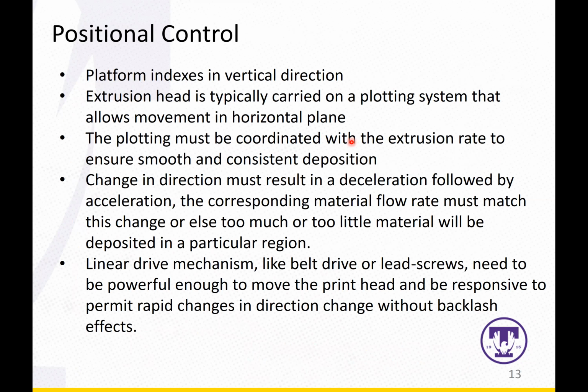So they will extrude a small amount of material onto somewhere, and after this they will move their printing head to print the actual layer, and that gradually, significantly decreases the chance of having a messed up layer because of this deceleration and acceleration in the printing process, right?